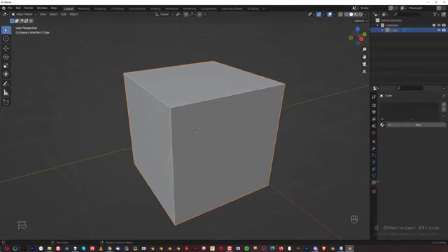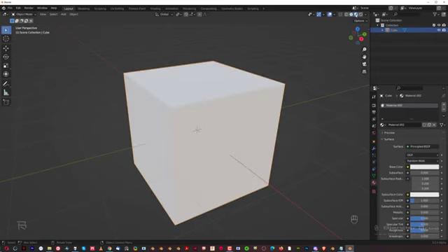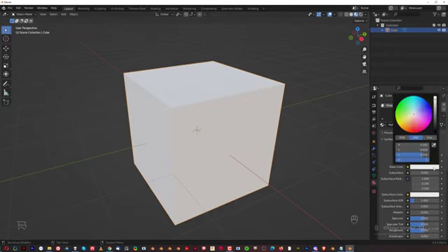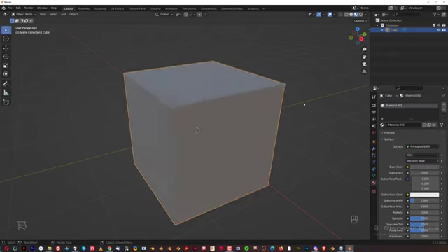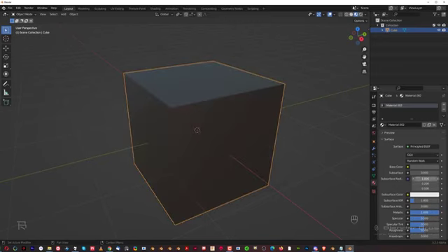Now this tab here is quite important because we're going to be using materials here, which means if I click on New, I'm automatically adding a material to the selected object. You cannot see anything in the viewport because that's not a rendered view, but if I switch to Look Dev, I will be able to actually see that material. So if I click here and make it darker, you will see we have some kind of preview going on. I can make it metallic, like this.